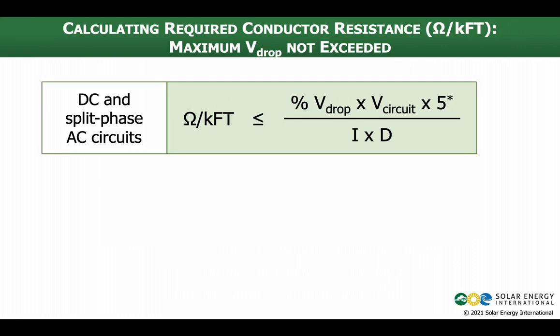Okay, that was voltage drop as a percent. We can do that for DC circuits, split phase AC, three-phase AC, but we could also do the calculation, flip it around a little bit, to solve for the resistance of the wire that we need. So what's the required conductor resistance to not exceed a maximum voltage drop level? This is something you might see on the AC side of systems in particular. Manufacturer says no more than 1% or no more than 1.5% AC voltage drop. That's what we're shooting for. So what size wire do I need to get that? Right? Instead of saying, well, this wire gives me this much and this wire gives me this much and this gives...